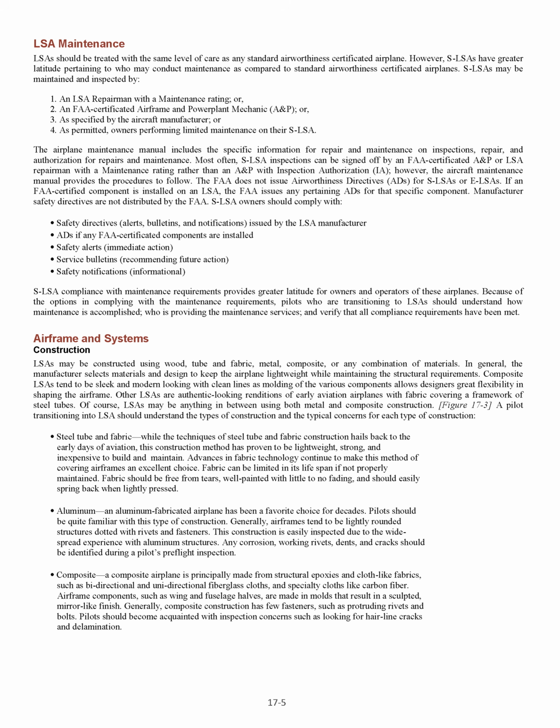However, the Aircraft Maintenance Manual provides the procedures to follow. The FAA does not issue airworthiness directives, ADs, for LSAs or ELSAs. If an FAA-certified component is installed on an LSA, the FAA issues any pertaining ADs for that specific component. Manufacturer safety directives are not distributed by the FAA.